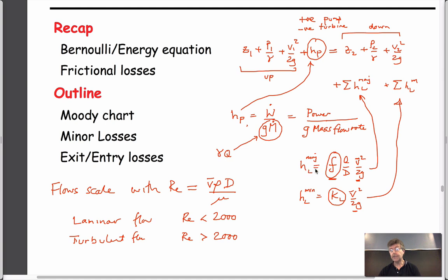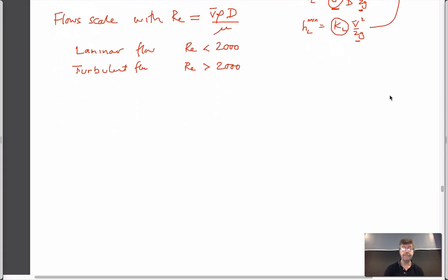The only difference with the friction factor in a pipe is that it's per incremental length of pipe, and so you have to multiply it by this incremental length to be able to scale it up to your full pipeline from New Orleans to New York City. This is done per fitting. And so you have one bend, you add one magnitude. If you have 10 bends, then you have 10 magnitudes of this to add. So that's the deal. Okay.